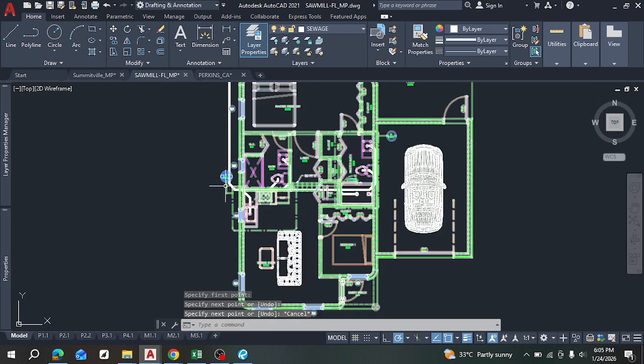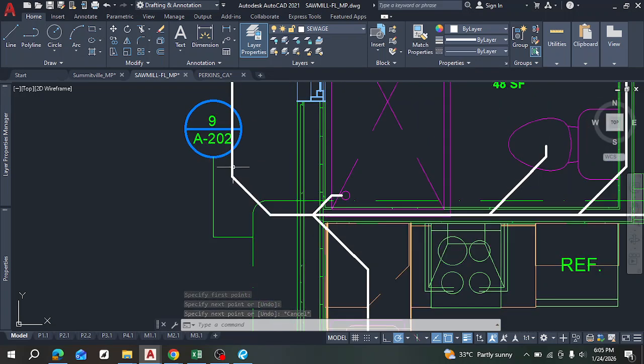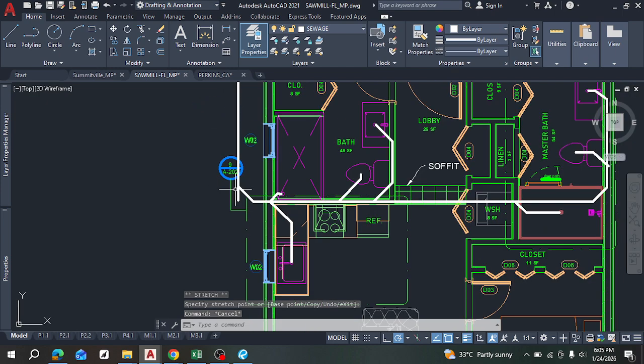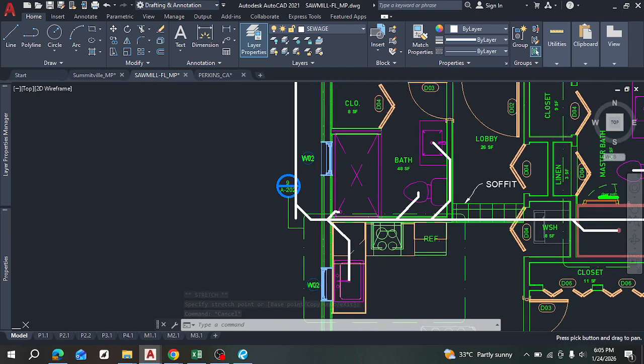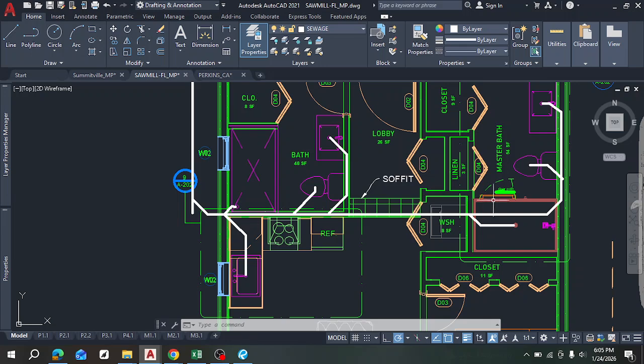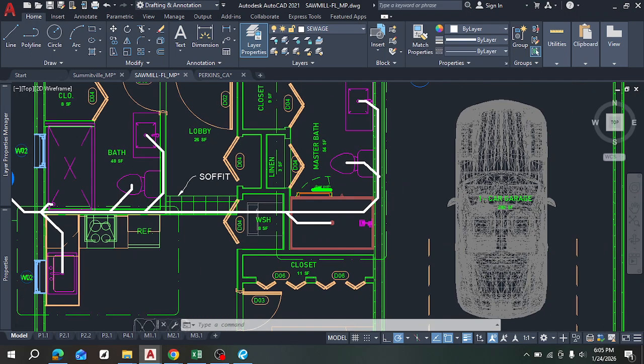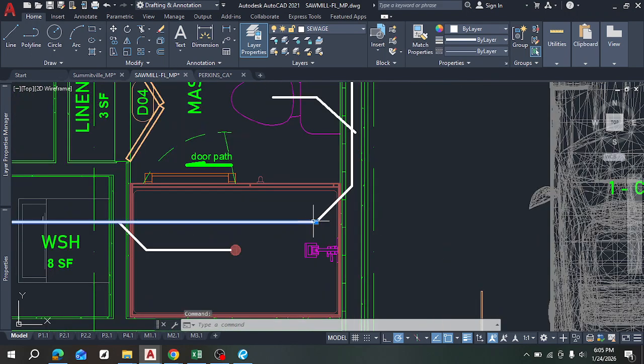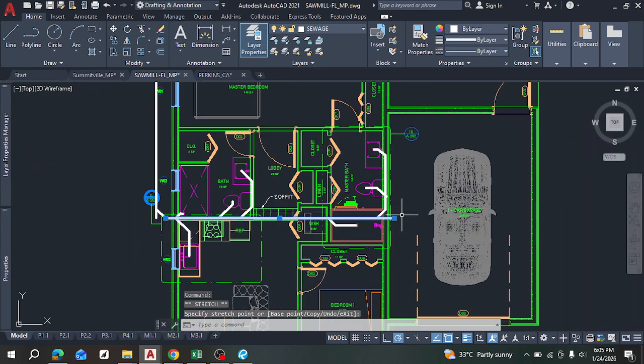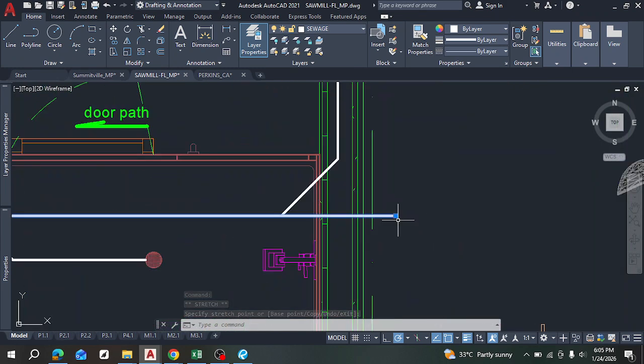Now let me add my clean out. I mean, I'm done at any point, but let's just do it. I mean, the earlier the better, so I don't have to procrastinate and then I'll forget like before. So there's a clean out here because the flow goes like this. So now this is outside the building, so it's not a problem, and it's at a change of direction, right? This is another change of direction, so I'm going to add it out here. Now if you notice, this would have been a problem if it ended inside this wall, but I mean, you can always extend to the garage, right?